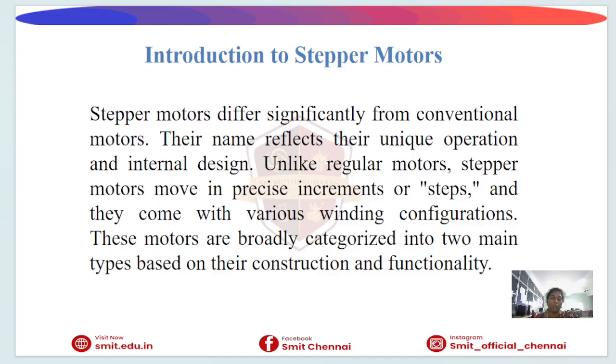First, we have the introduction to the stepper motor. The stepper motor converts electric pulses into mechanical movement. Each pulse sent from the microcontroller rotates the motor by a small fixed angle, that is the step angle. If the step angle is 1.8 degrees, then there are 200 steps per revolution.